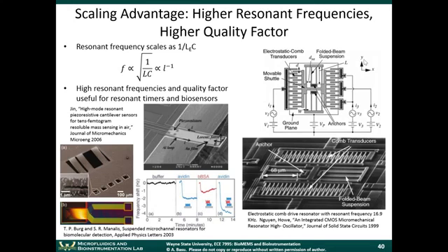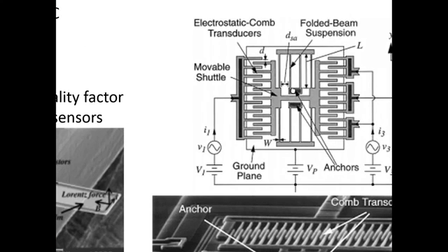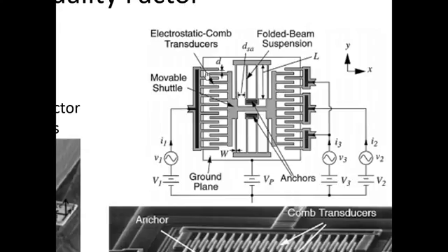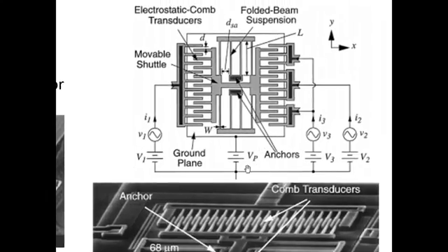It's the same idea here, except you have a series of beam elements here. You apply a voltage between this element here and this element here. That causes the attractive force between the plates, and that causes the device to resonate in the in plane. So it's sort of in the y direction here. I'm sorry, in the x direction.